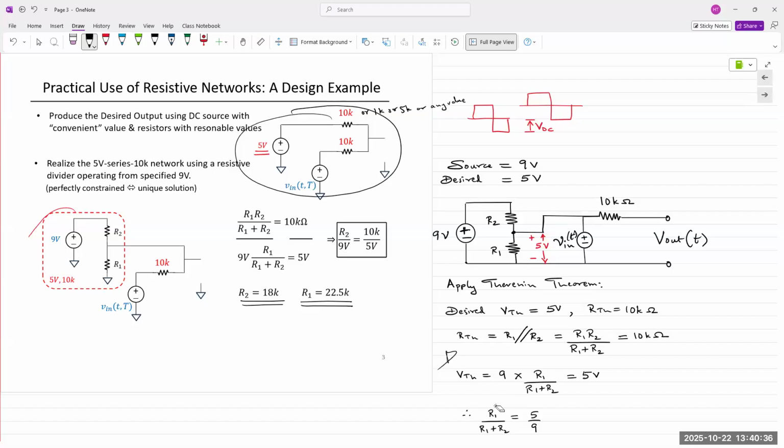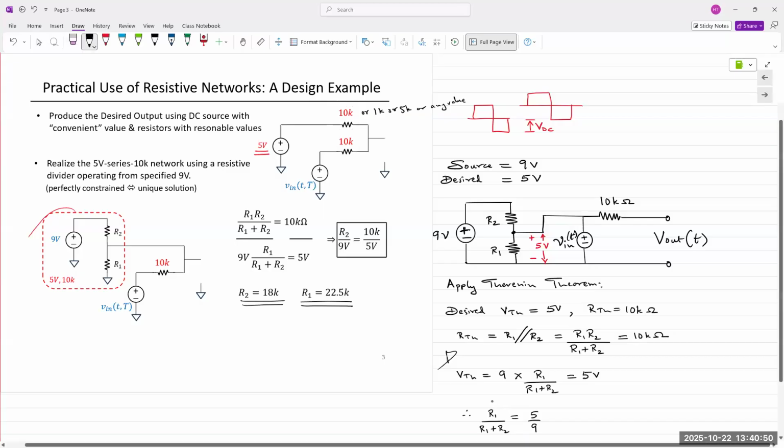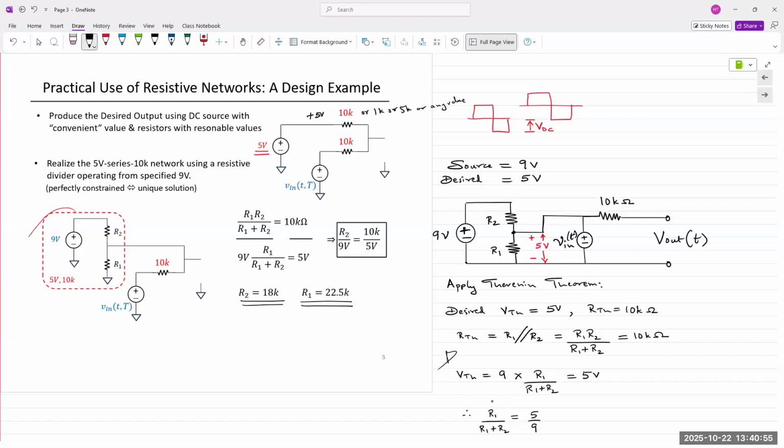It's a good point, but we have resistors here equal in value, and so they will cause a voltage drop across those resistors. So this is at a constant 5 volts, right? If this waveform goes from -5 to +5, if that waveform is also at +5, then the current at that point is 0. So there is no voltage drop here.